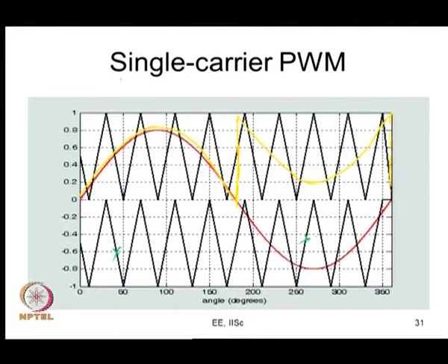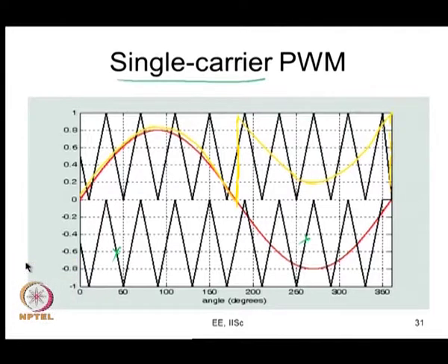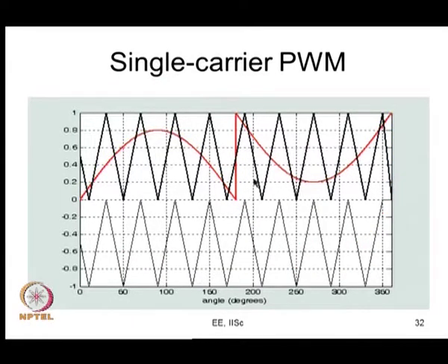So, you do what is a single carrier PWM. Like we have one sine wave on 2 carriers, there are also methods where you use 2 sine waves on 1 carrier, that has also been discussed in the literature. And now, this is some modification of your in phase carrier PWM, so that you can use just a single carrier by phase shifting your signals. Alright. So, this is what I have shown plotted here. This is something you do in your PWM generator, and you do your comparisons based on that. So, that is an easy way of implementing.